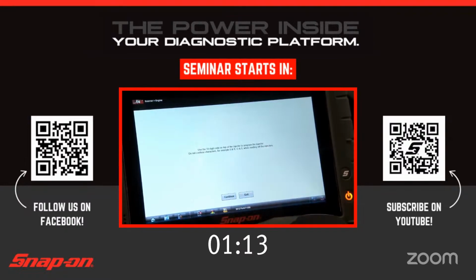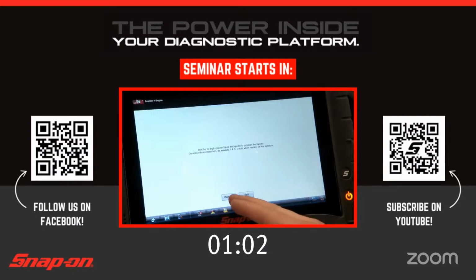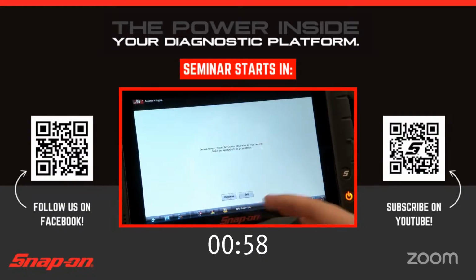It says use the 10-digit code on top of the injector to program the injector. Do not confuse characters, for example, 8 and B, D and 0, when reading off the injectors. So I already wrote down the code on the one that's in there, so we'll hit continue. On the next screen it says record the current IQA codes for your record and select the injectors to be programmed. So we'll hit continue.